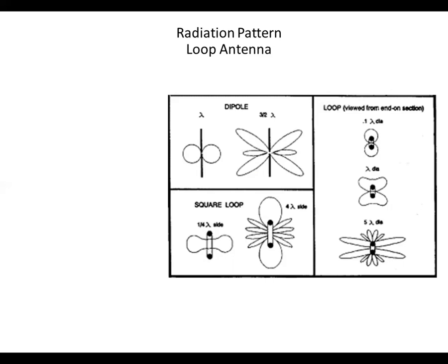They do have applications, generally lower power. They do better with higher noise environments. They're not as susceptible to noise as, say, the vertical or the horizontal dipole. So it would be a consideration, but the radiation patterns are quite different depending upon the fractional wavelength that is driving the antenna.